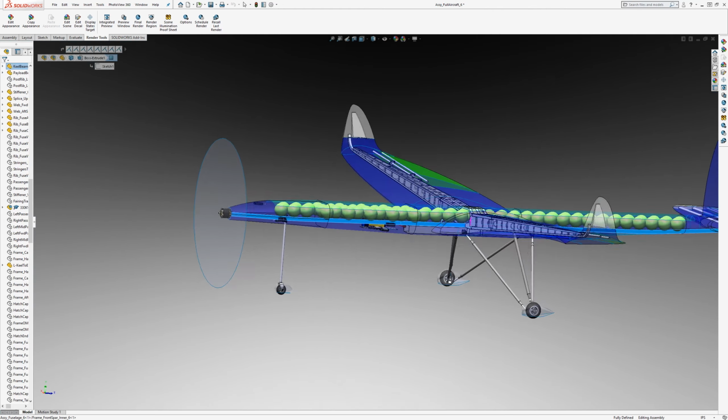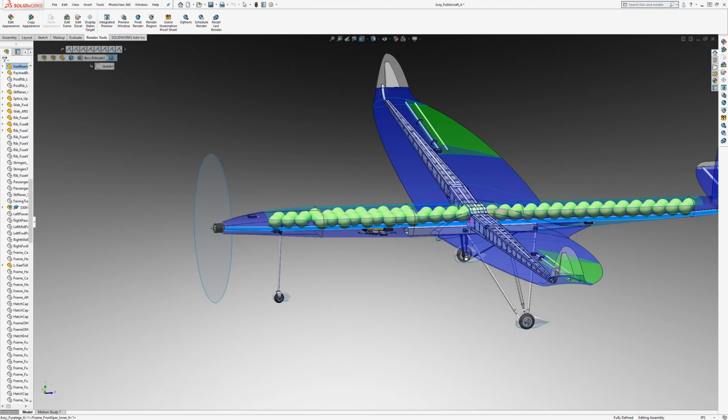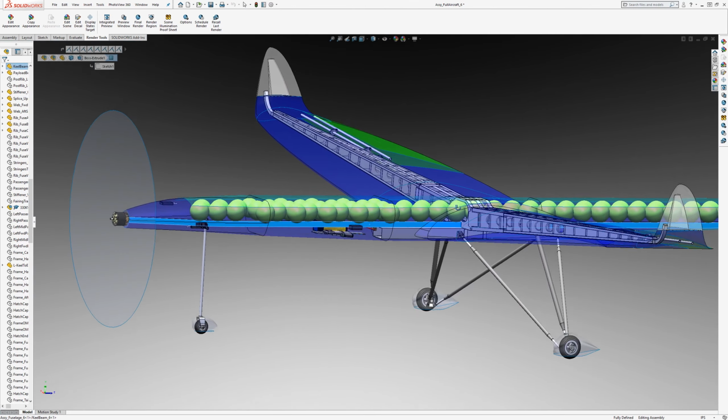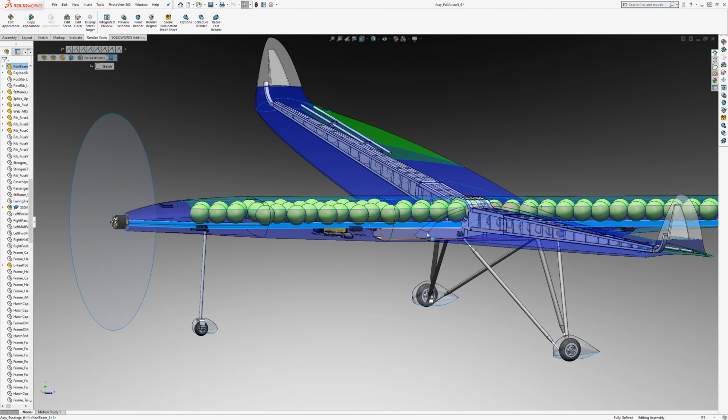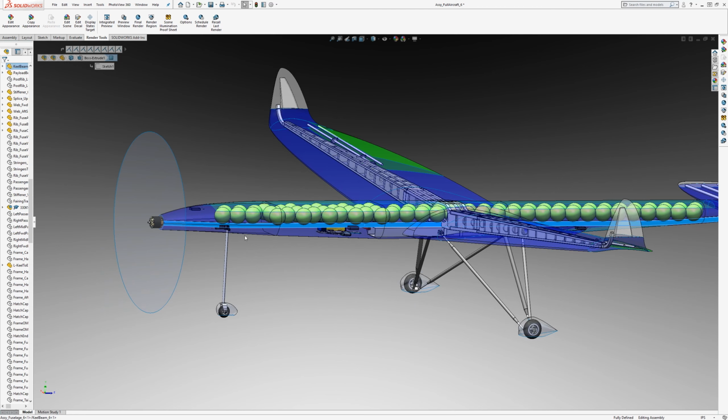But in terms of the terminology that we're talking about here, external loads means applied loads. So the inertial loads, even though they're coming from within the structure itself, we're going to call them external loads. They're applied onto the metal. Whereas the internal loads, the shear and moment that we're going to calculate, those are the accumulated loads within the structure that it has to resist to keep itself together.